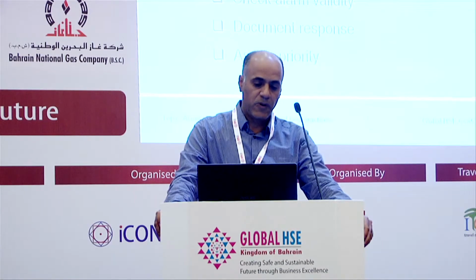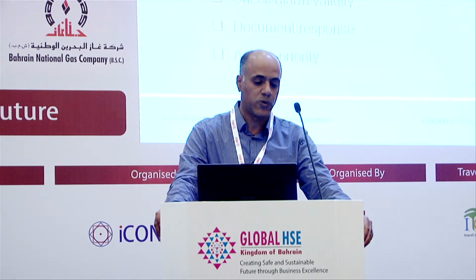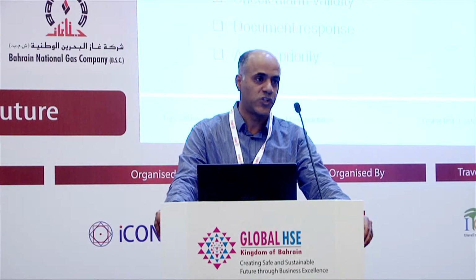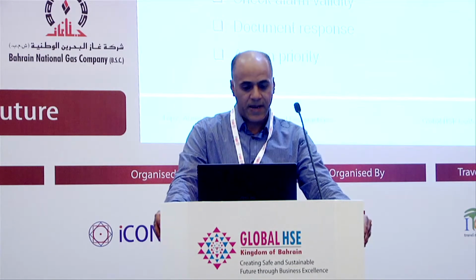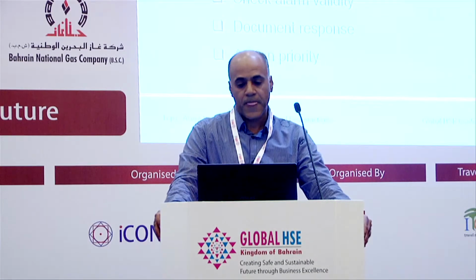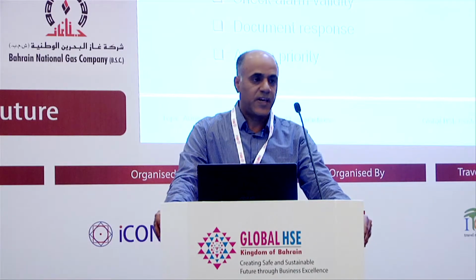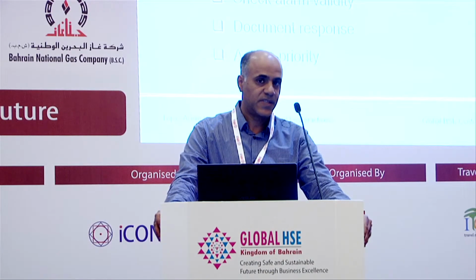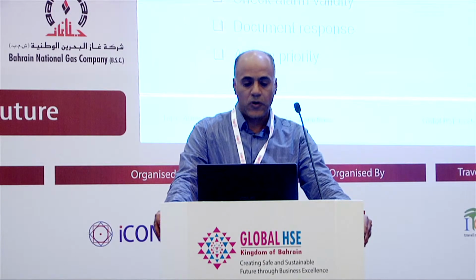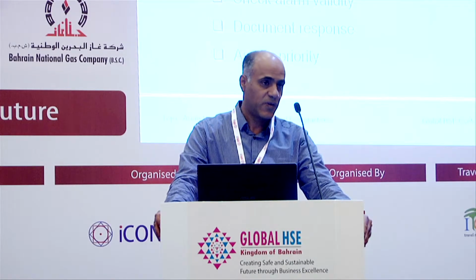The philosophy will involve the procedure and defining of alarms, alarm selection and presentation, how to control change, so you cannot leave the alarm set point change open to the operator, and how to assign priorities. In addition to that, we have to assign the responsibilities, and we have to do the training. All that has to be done within the philosophy.